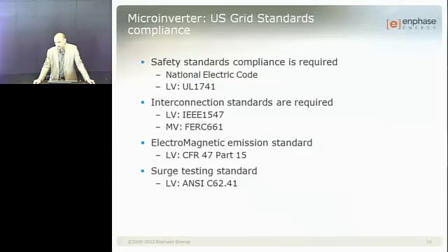As far as safety, we comply to a standard from UL, Underwriter Laboratories, which is UL standard 1741, which describes exactly what tests should be done to make sure that the inverter is built in a safe way and will not present a risk to the users. So we're not done there. We still need to go to interconnection standards. Now that we have a safe product, it doesn't mean that we can interconnect to the grid.